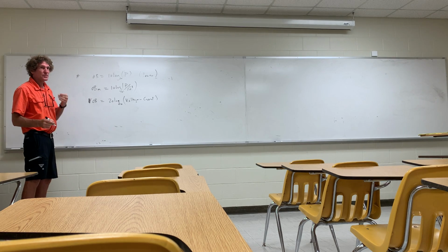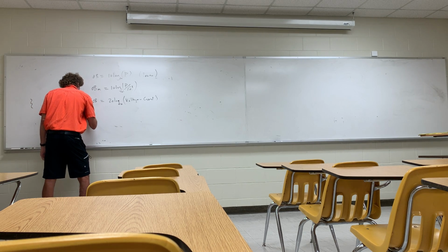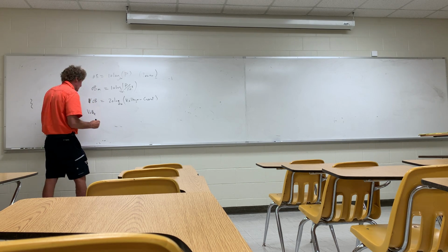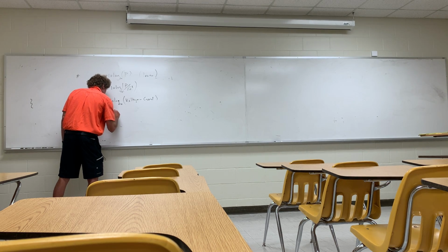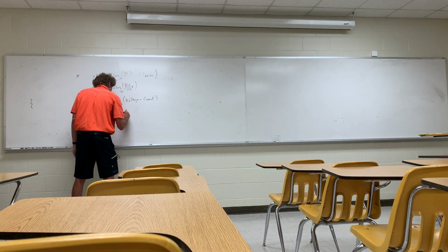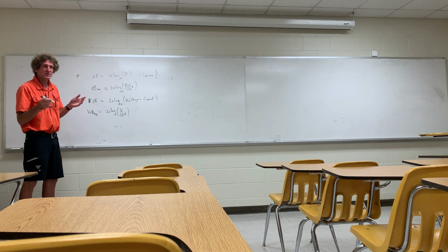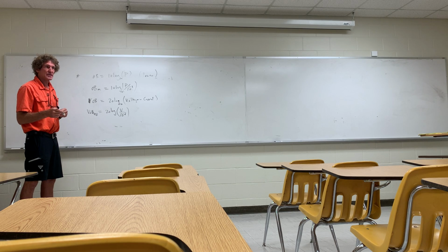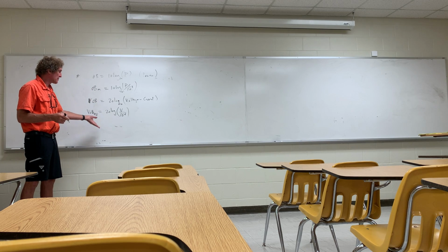What's really common when you're talking about a voltage decibel measurement is called the voltage in dB microvolts, or just put micro. Usually, sometimes you do UV, and that's 20 times the log of the voltage over 10 to the minus 6. Y'all follow? And dB microvolts are used all the time in measurements, especially when you're dealing with things related to cellular activity, cell phones, Wi-Fi routers and stuff like this. Almost always dBm and dB microvolts with voltage or power.